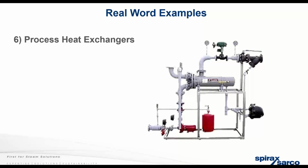And then we look at the process side. It's one of those things where in today's energy efficient world, we're really not looking at the process side so much. So if this heat exchanger is heating a building or heating a plant, and I'm not carefully monitoring the pressure, if I'm trying to save energy at night, and I'm changing the flow and/or the pressure of my process system, potentially under a no flow or low flow situation, I could have a call for steam, and my steam pressure on the steam side is greater than the steam on the process side.